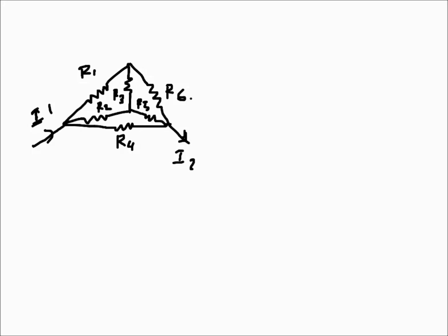So we have to find the equivalent resistance of this whole block. What it's actually trying to say here is current is going this way and coming out that way. If we make an observation, this one, let's call it node 1, node 2 and node 3, these three. So there is a delta connection here. You can see this one is a delta arrangement.